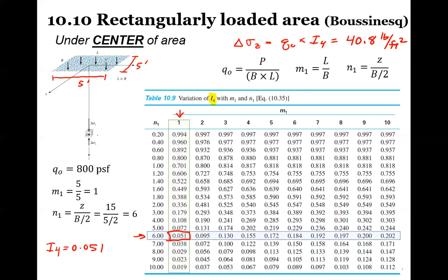So the 2-to-1 method provides a rough estimate that is over the typical actual value the soil could be feeling. It is generally conservative, which means we are overestimating, so our design is overly strong. That's not a real term, but you get the point, hopefully.